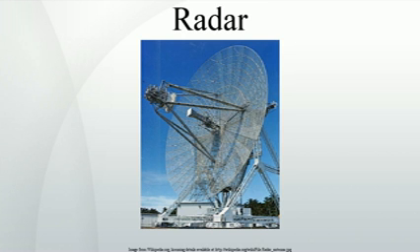Early radars used very long wavelengths that were larger than the targets and thus received a vague signal, whereas some modern systems use shorter wavelengths, a few centimeters or less, that can image objects as small as a loaf of bread. Short radio waves reflect from curves and corners in a way similar to glint from a rounded piece of glass. The most reflective targets for short wavelengths have 90 degree angles between the reflective surfaces.